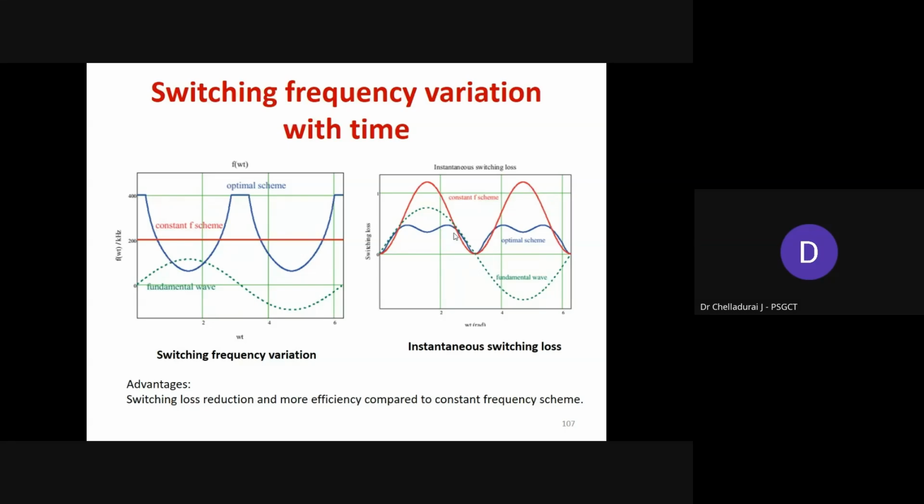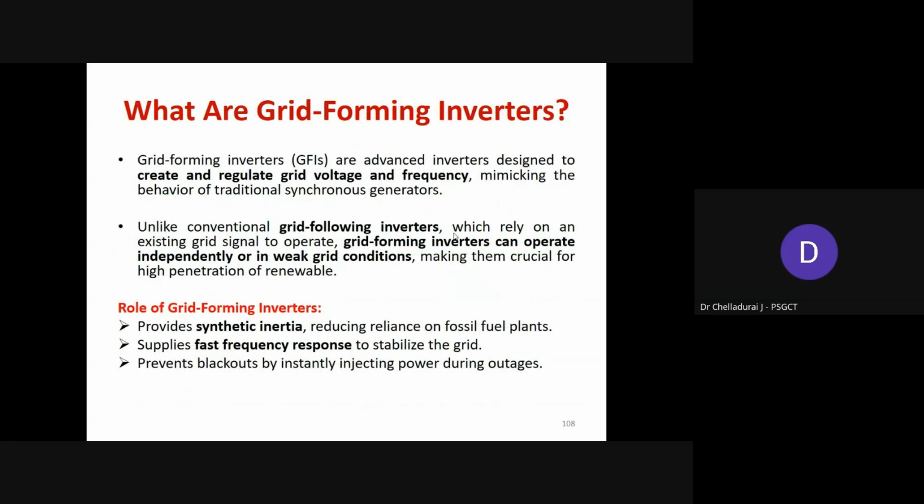So those interested can try to implement this particular concept: variable switching frequency with respect to the output voltage wave shape over the period of one full cycle. Then another very interesting piece of information, the recent trend in grid-connected inverter topology is grid forming inverters.